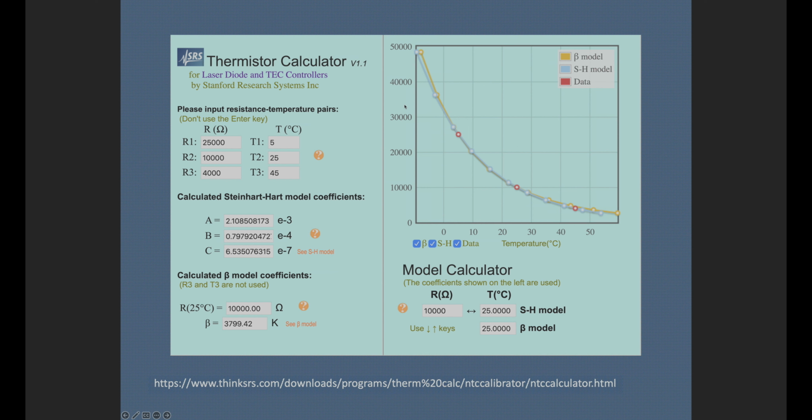What we're going to do is take temperature readings on our extreme ends and one in the middle. We're going to take the temperature reading now on the cold side. We've had the silicone oil in the refrigerator or the freezer overnight. And as the temperature goes up, we're going to take readings. We're at minus 4.3. And right now, with the resistance, we're looking at the epoxy thermistor. And we'll switch over and look at the Honda coolant temperature. Take a reading at that temperature.